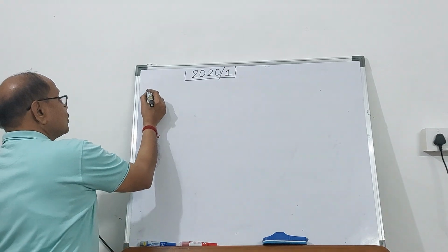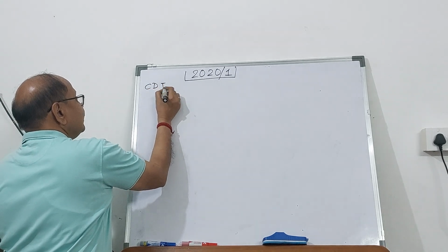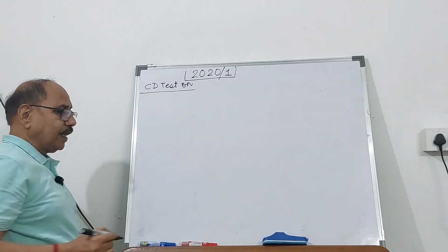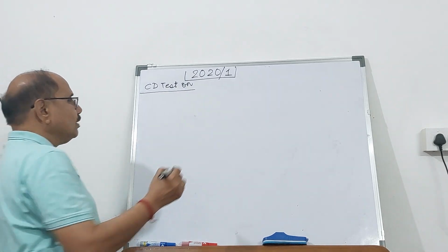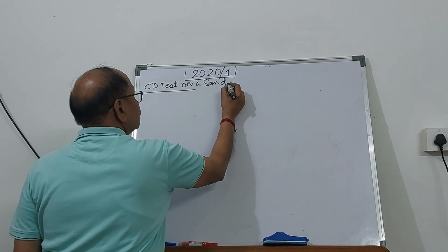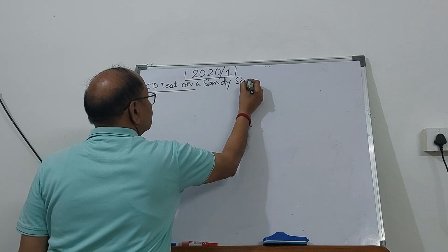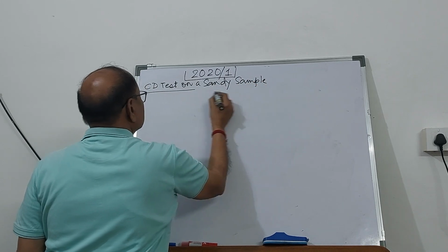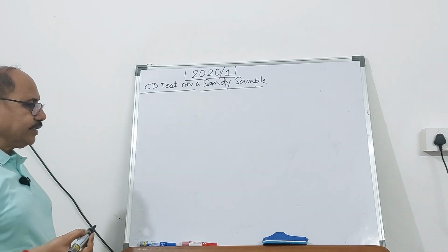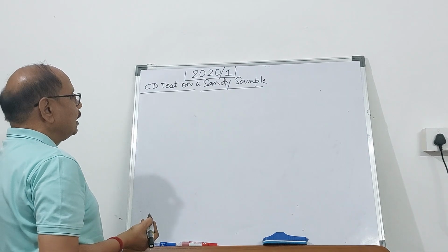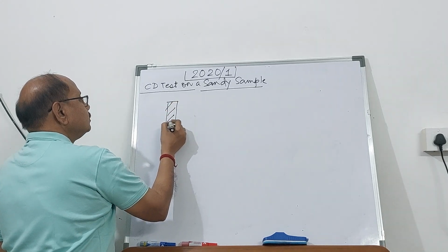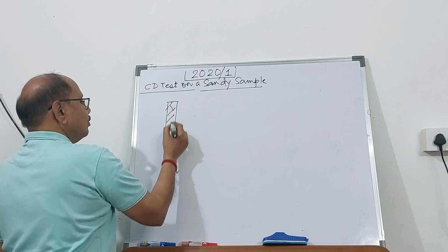It is a CD test, consolidated drained test on a sandy sample. So the sample is granular material, it is sandy soil, and this is the sample in triaxial compression.